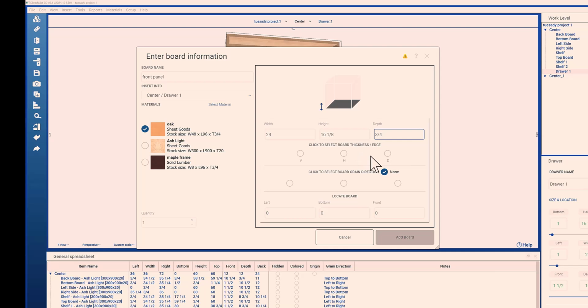To produce images, cut lists, and optimized diagrams, SketchList needs to know which of these three dimensions is the thickness. And it is almost always the thickness of the material. Sometimes it might be different, if you had solid material with a thickness of 2 inches or whatever.